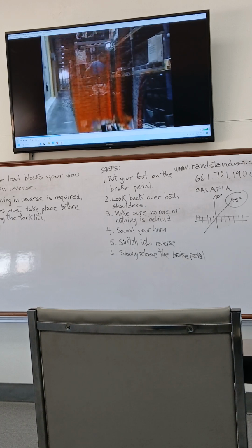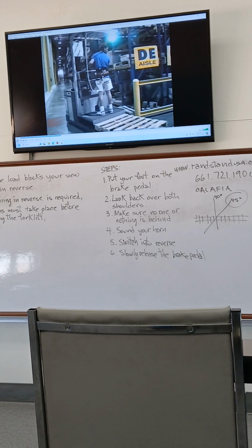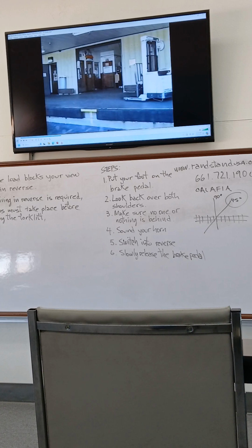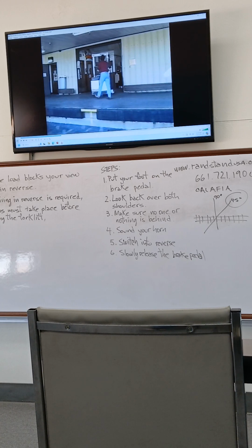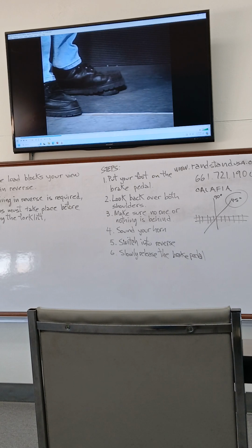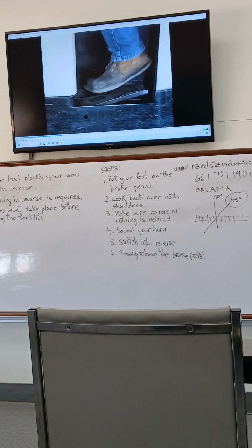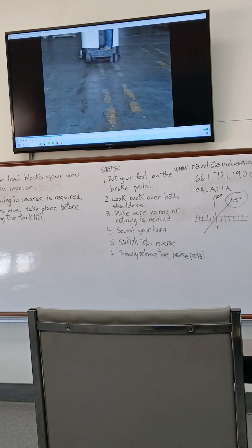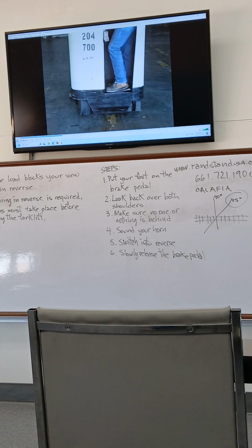Others may employ mechanical systems actuated by electronic solenoids, such as order selectors. Still others, similar to walkie pallet trucks, have mechanical systems. On many electric trucks, when an operator removes his or her foot off the electric forklift accelerator or standing pad, friction stops the electric forklift. It's a different sensation, and stopping distances are somewhat different, again pointing to the need for training and getting used to the different type of equipment.